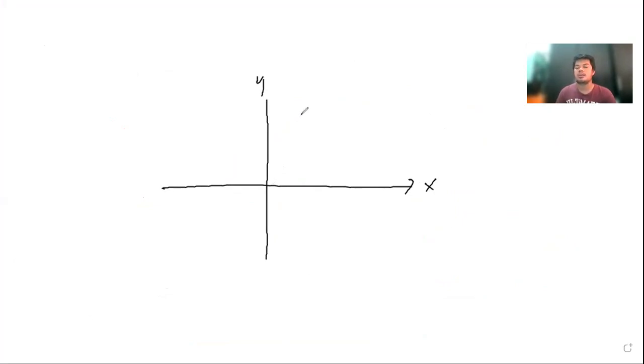For simplicity, we can say that we need to have one of the forces given in the problem to be our reference. So we have F1 here. The resultant force, according to the problem, is 90 degrees away from F1. That is why we need the reference, because we need to plot the resultant force, which is 90 degrees from F1.